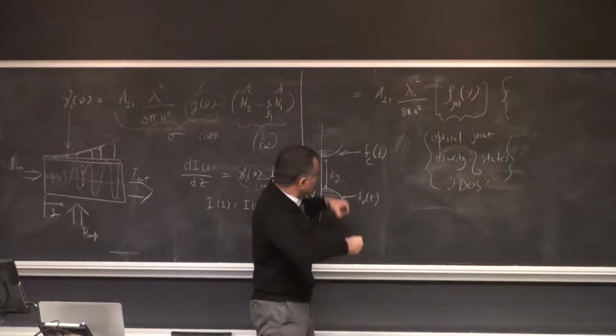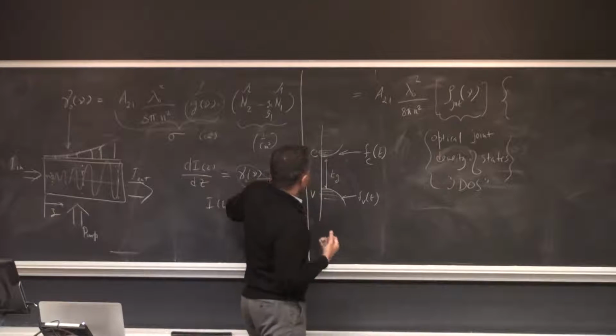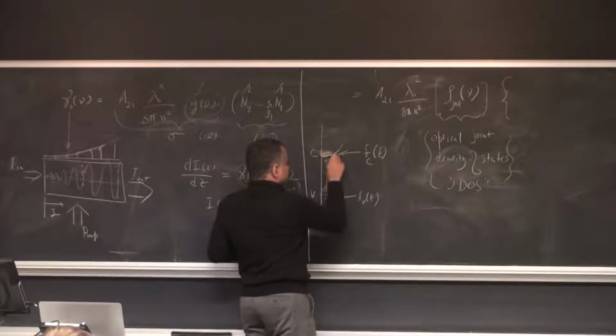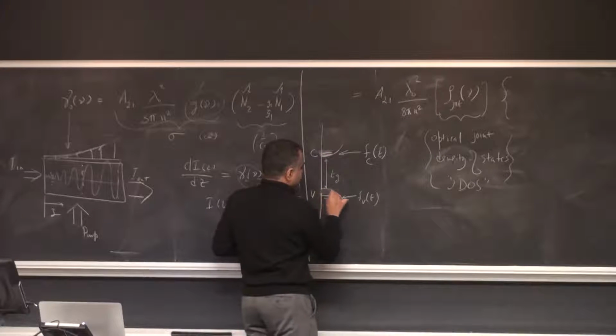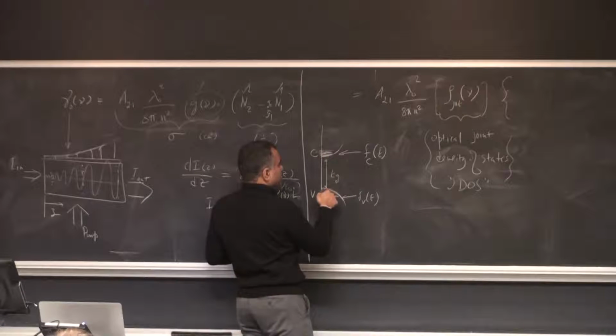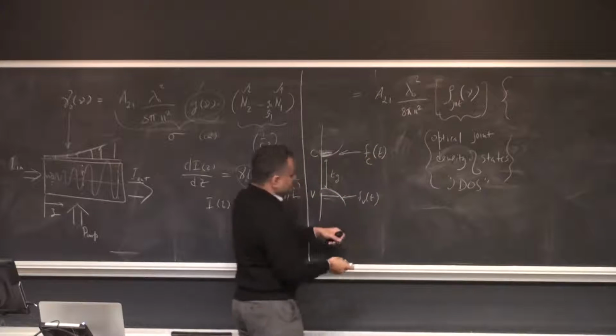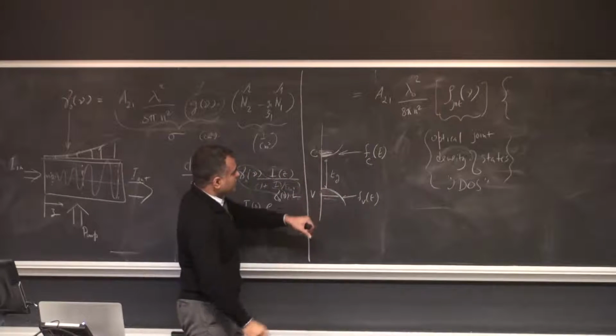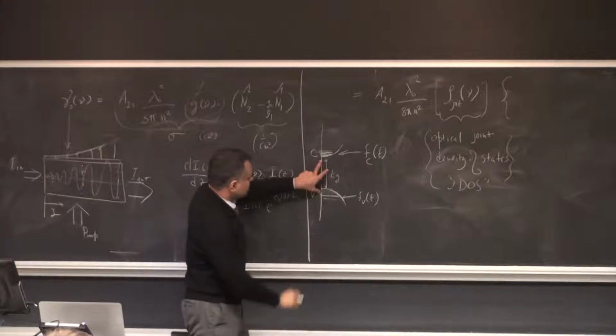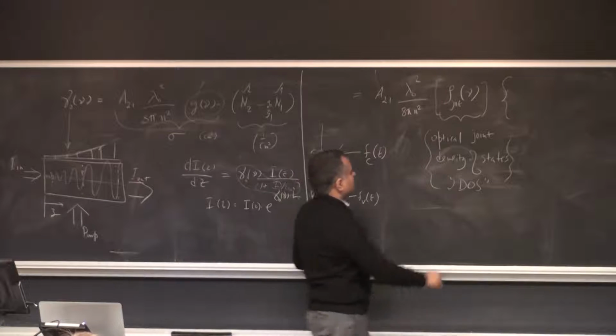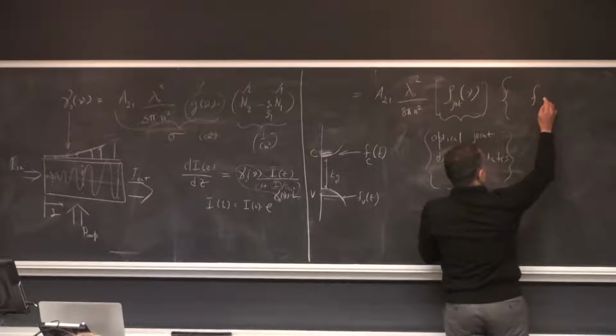So I'm going to pull it way out of equilibrium, and I'm going to invert it. I'm going to put a lot more electrons here, and I'm going to empty out a lot of states here. So that will be electrons, that would be holes. And this measure of how far out of equilibrium you have pushed the semiconductor system is given by the difference of the Fermi functions.